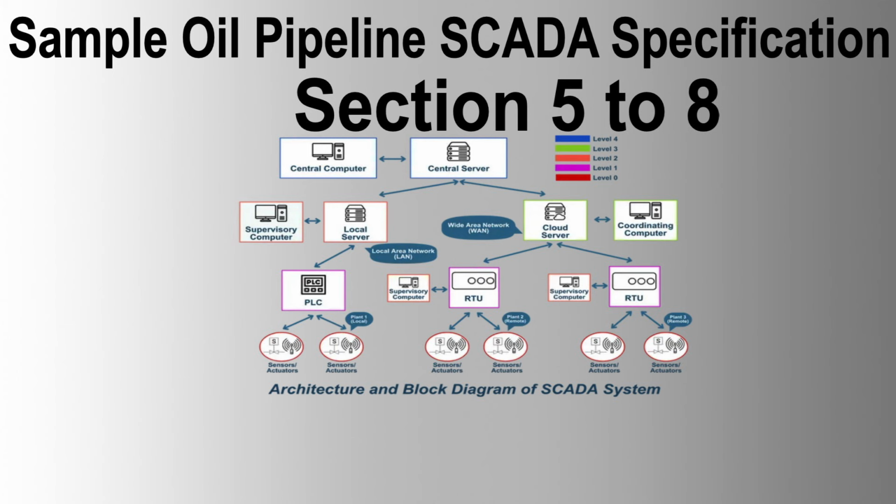7.4 Program structure. All compiled software functions shall be constructed from individual modules with clearly defined interfaces. Each module shall provide a specific component function and be designed to ensure changes in one module require no changes to any other module. Programs shall be well documented with reasons for each module, notes explaining calculations or logic, and references to logic diagrams.